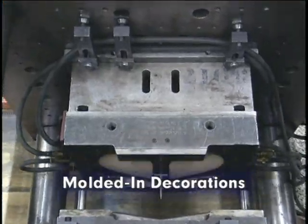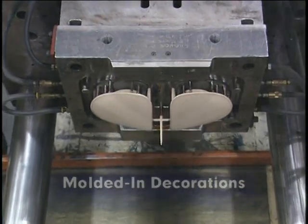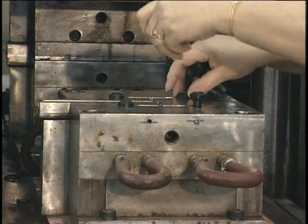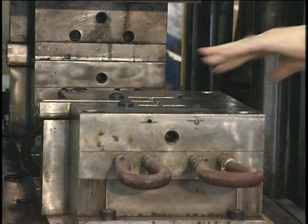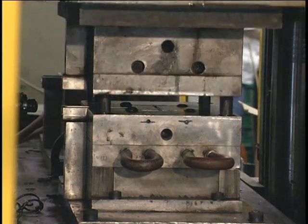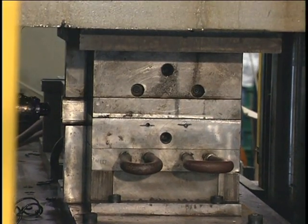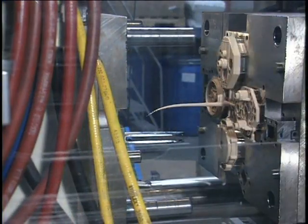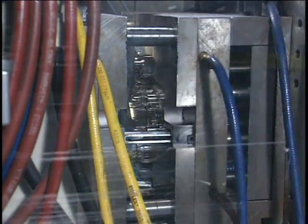Molded-in decorations are those machined into the mold, such as textures, or by implant, as with two-shot molding, where an insert is placed into a mold and then molten plastic is injected around the exposed areas of the insert, creating the part. Even pre-colored plastic resins are considered molded-in color.